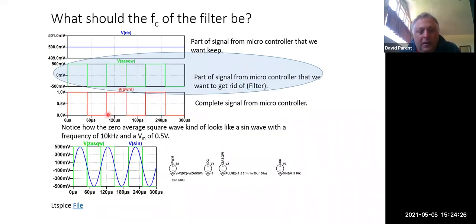So again, just looking at this intuitively, what fits into this square wave the best? Well, a sine wave. Now, sure, over here it's underestimating it, and here it's overestimating it. But that's just a Fourier transform of two things: you have the DC offset, and you have one sine wave.